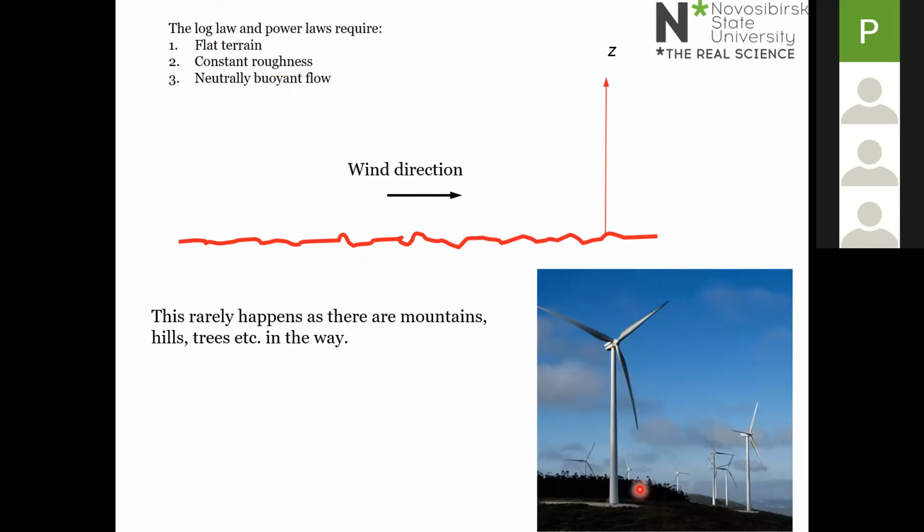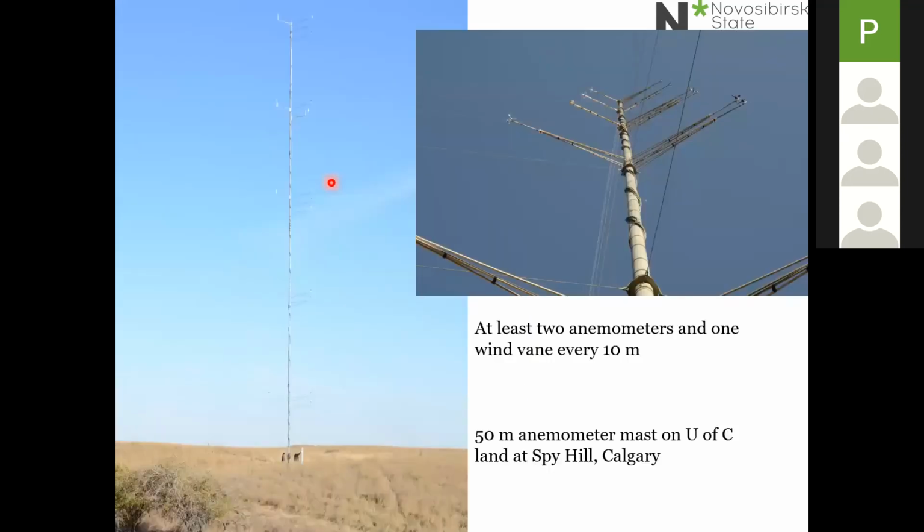Often wind farms are sited on hilly locations, and the roughness around the turbine can change, and that can influence the way in which the wind speed varies with height. So what that means for wind turbines, and particularly at the stage when you do wind resource assessment, is that you need to get information that is as close as possible to being representative for the hub height of the wind turbine.